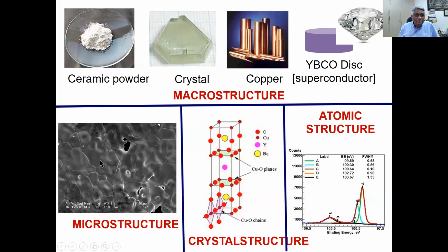This zone is a single crystal, the neighboring one is a single crystal, but the grain boundary is a defect, in the sense that the regular atomic arrangement is terminated there. The crystal structure formation is not there, so you'll have loosely bound atoms there. Loosely bound atoms are not good, and grain boundaries could also be inlets and outlets for oxygen, if it is an oxide compound.